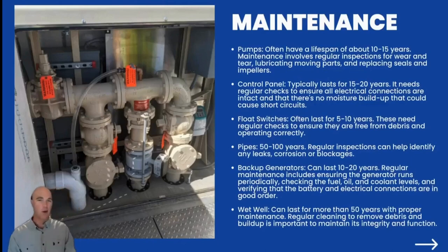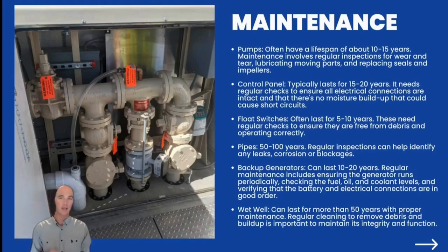Okay, so what kind of components should we be maintaining? I'm just going to go through again a lot of them that we talked about earlier, what the components are, and talk about their lifespan. So the pumps, it's pretty normal to have pumps last around 10 to 15 years. That inspection is going to be pulling the pump out, looking at it. There are different seals, checking the impellers, seeing if those need to be resurfaced, and adding any kind of lubrication, like you do with a bike. You've got a bike, your chain gets hard to move and not smooth. Sometimes you've got to add some sort of lubrication.